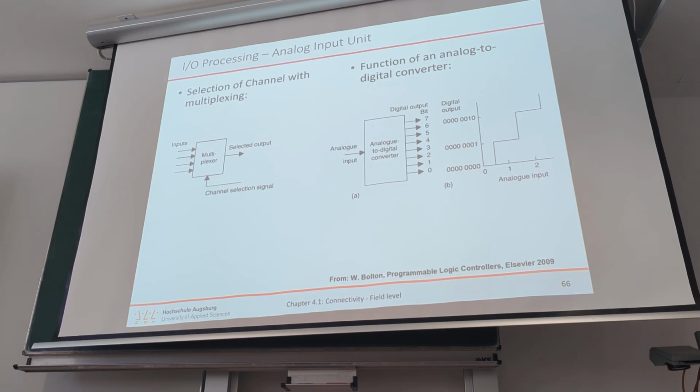They are sampled after each other, and we already heard that usually we want to have a snapshot of the input state for control logic, and here we sacrifice some of the time by sampling the inputs one by one, but that makes the whole system a lot cheaper.